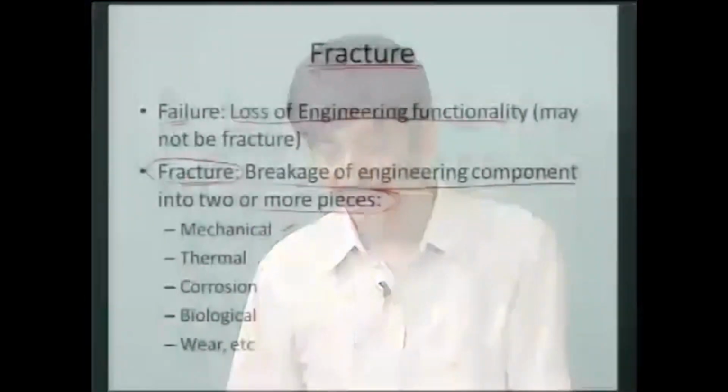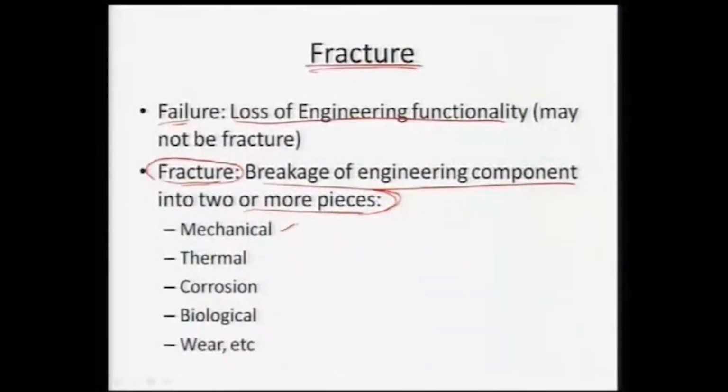And this fracture can be through mechanical load. If I apply very high stresses or very high load to a component which it is not designed for, then the component can fail or fracture. Thermal loading: if I thermally load a particular component, it can fracture, because at higher temperature the strength of the material starts degrading. Depending on that, it can fail.